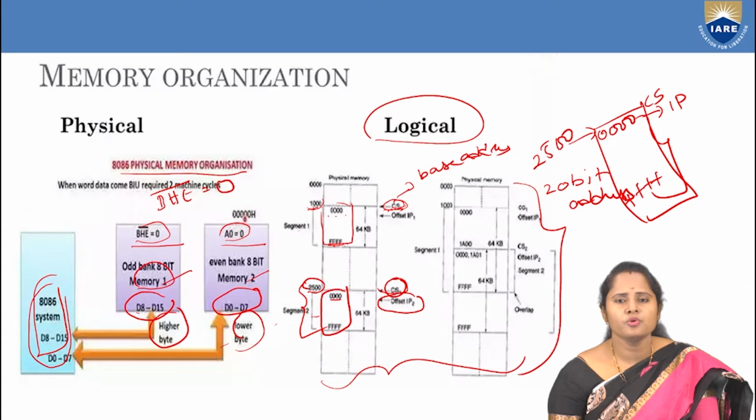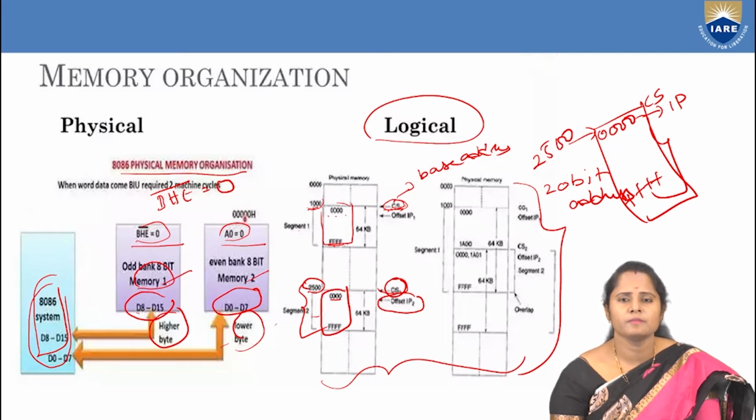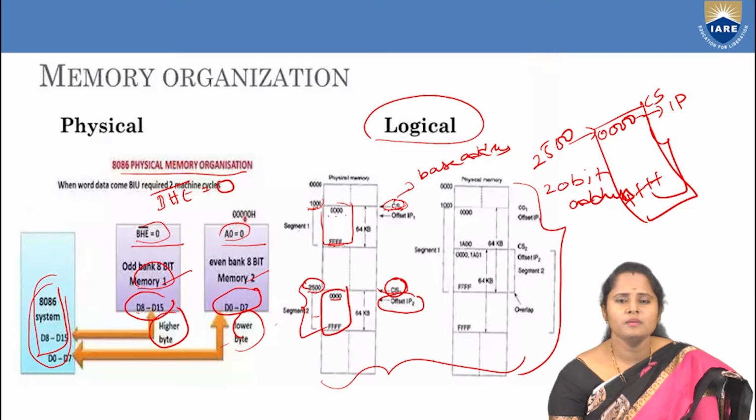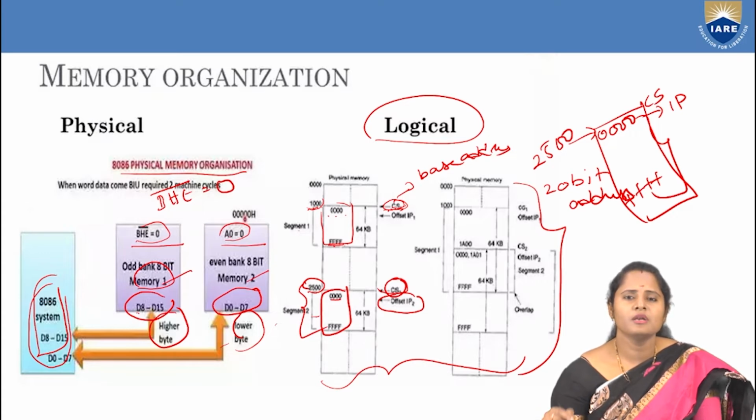So first you need to generate a segment address of 20 bits by adding 4 bits to the LSB. Then the code segment address is generated as a 20-bit address, and that 20-bit address you add to the instruction pointer of the code segment which you are working in, which is 16-bit.